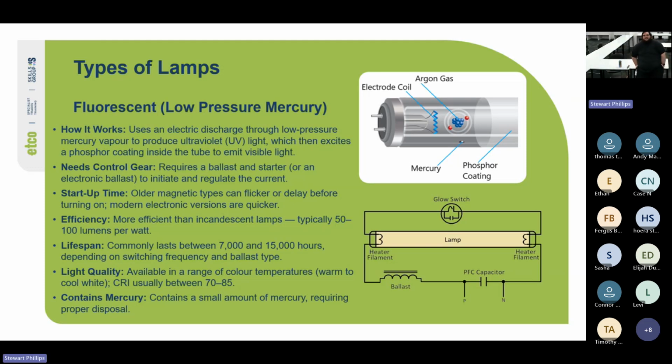So they do make LED tubes. What you can do is remove the ballast inside the fitting, put in a driver, and put LED tubes inside the fitting. So if they don't want to change them out because they won't match, you can say, well, we can swap out the ballast for a driver, and you won't notice the difference once all the lights are on.